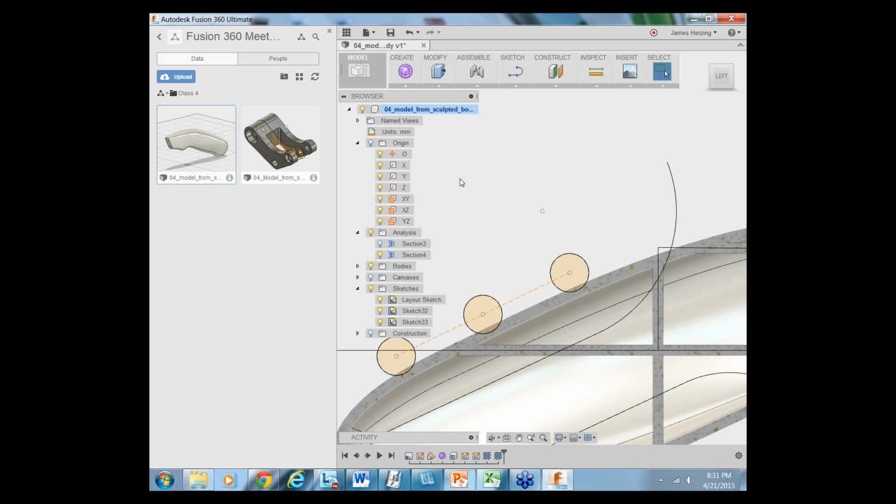If you're in the sculpt environment, you can do many, many commands, but they aren't actually recorded as individual steps in the progress bar. You could do like 5 commands in the sculpt menu, and you get one wrong. You could only delete the whole step. You can't step backwards in a sculpt menu.